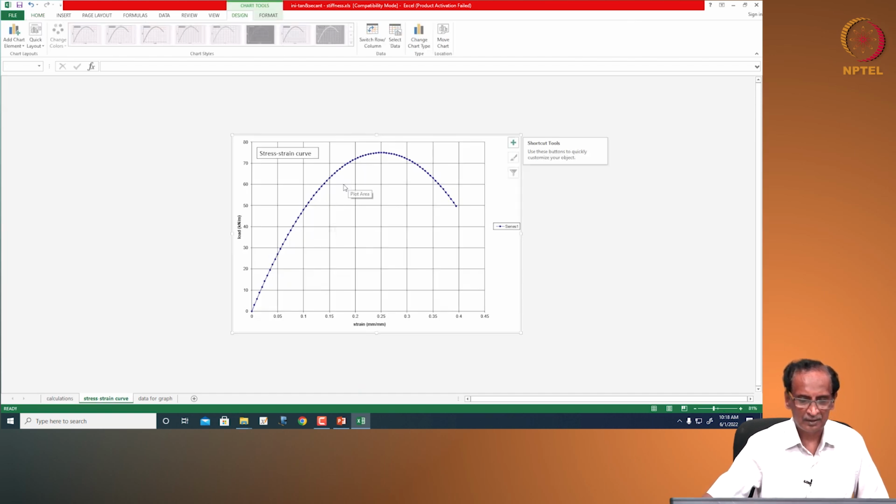See here, this is the stress strain curve that we have, and we are trying to solve for the strain at a stress of 65. If our applied stress is very close to the peak, then we need more iterations, because you see here there is a lot of non-linearity, and if it is only 20, we are still very close to the linear limit.